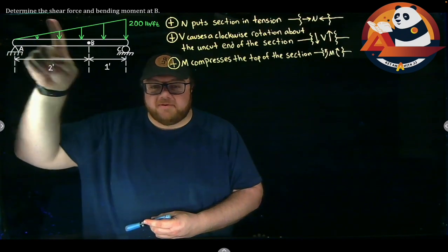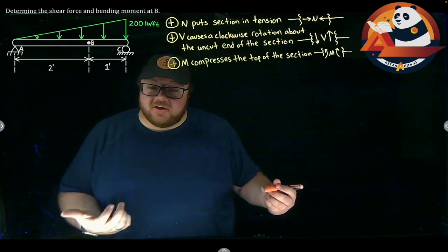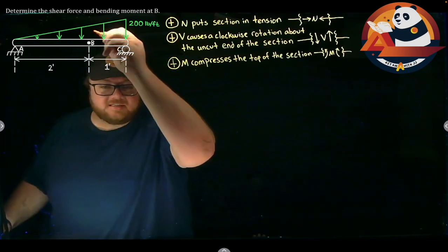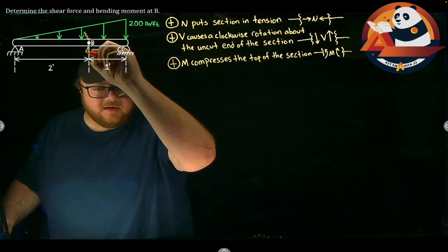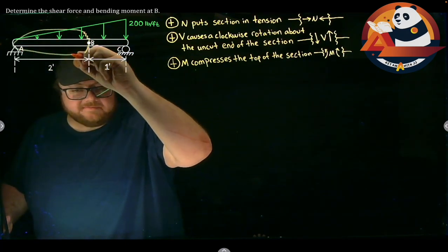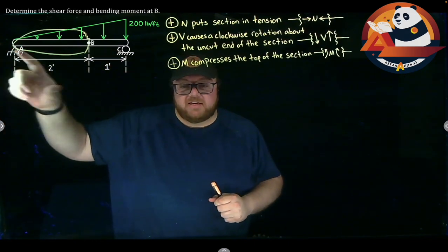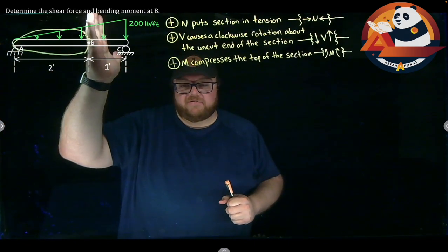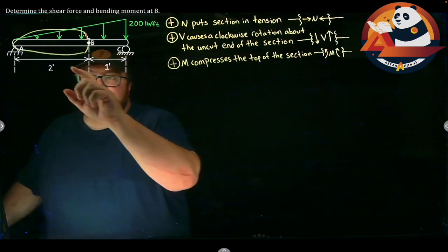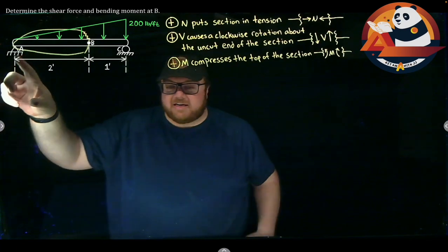So we're saying, let's determine the shear force and bending moment at point B in here. To do this, we're going to set up a section where I slice straight through point B, and then I'm going to make a free body diagram that goes around through point A. If we can include the tip of a triangle when we do these, it will always be easier than trying to figure out a trapezoid and working with that. So let's do circling to the left. If I'm doing that, I need to figure out AX and AY.